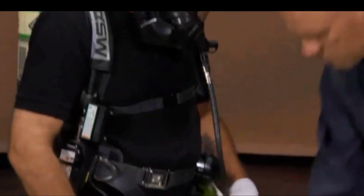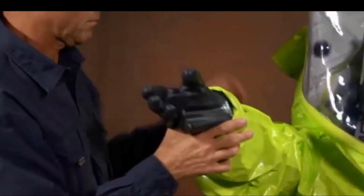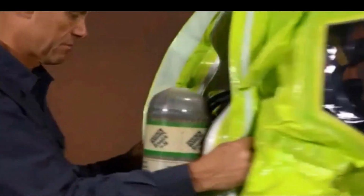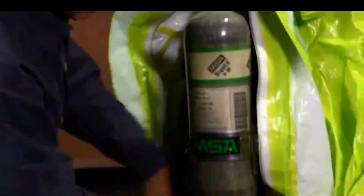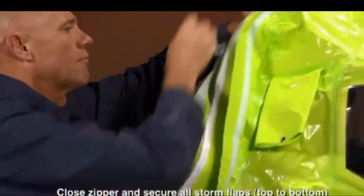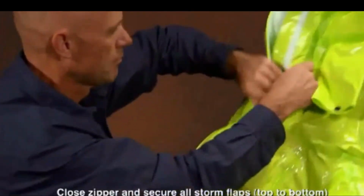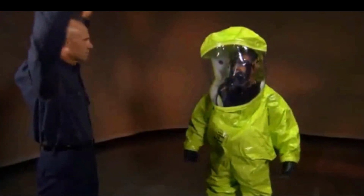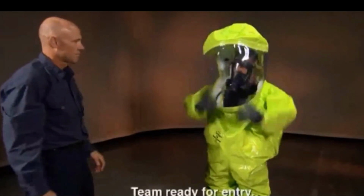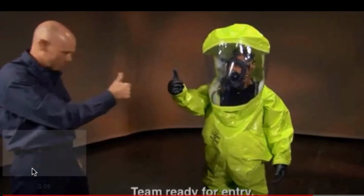Put on inner gloves if required. Stand up and reach both arms up, then pull upper part of suit over your head. Reach arm into suit down to the gloves. If the rest of your team is ready to go, attach breathing air supply and begin breathing through your SCBA. Close the suit by closing the zipper and secure all storm flaps. Check for range of motion and your mobility inside the suit. Proceed when your team is ready for entry.